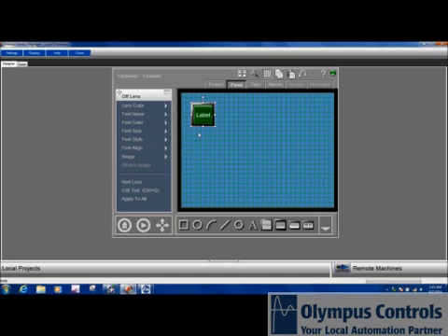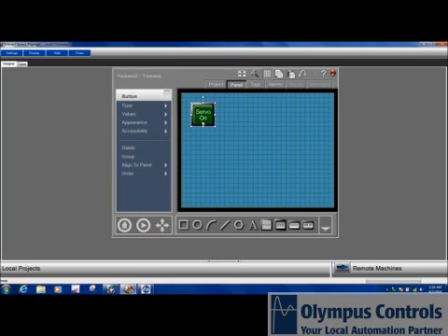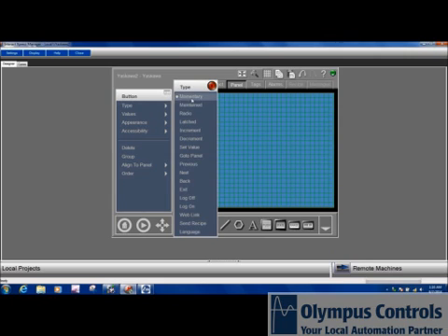And I'm going to use this push button. I'm going to change its appearance and the off lens. I'm going to edit the text. And I'm going to call this servo on. And the on state will be servo is on. Okay. I can do a test run and I can look and see what this button looks like in runtime mode. Okay. Now I need to connect this button to the PLC so that when I push this button it changes the bit in the PLC that enables the Yaskawa Drive. The type of button is just momentary.